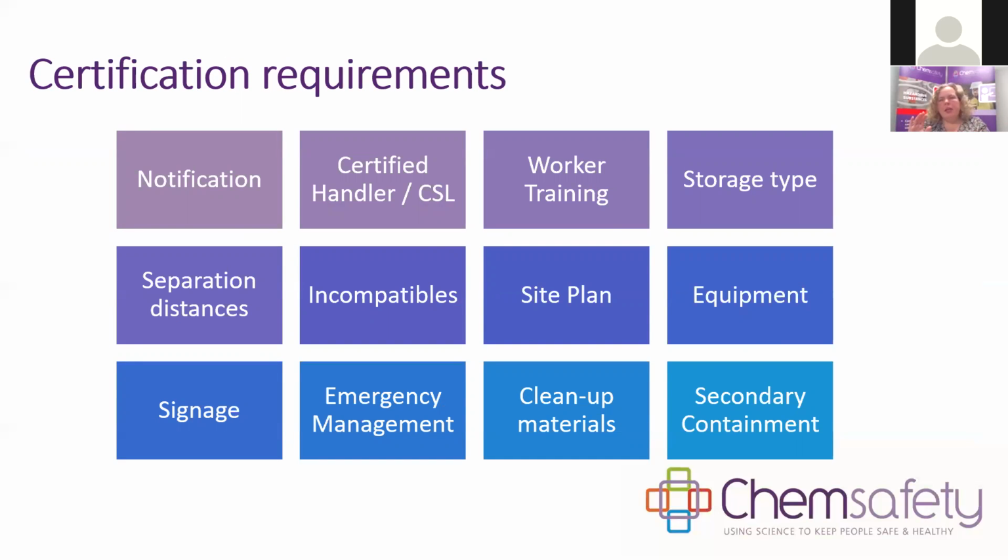You're going to need a location compliance certificate if you have your substances at a hazardous substance location. So it's a similar process to what you may be familiar with for your flammable or oxidizing substances. But in the case of toxics and corrosives, that certificate can be issued for up to 3 years.